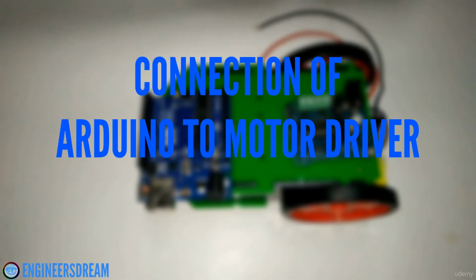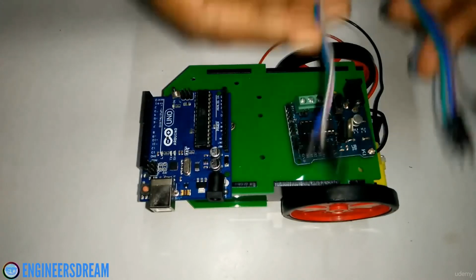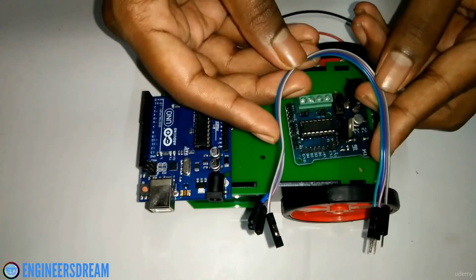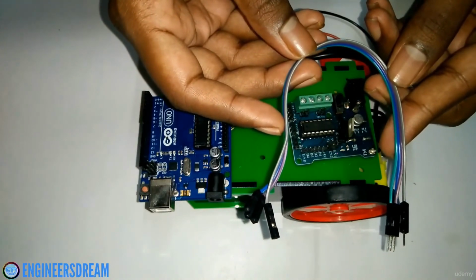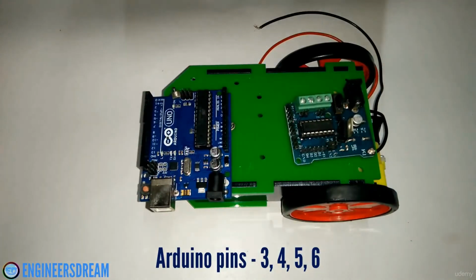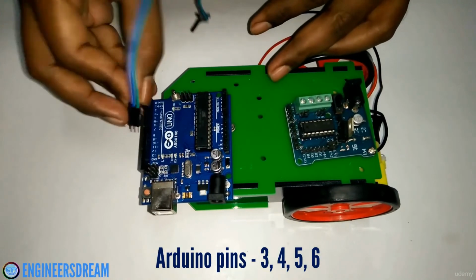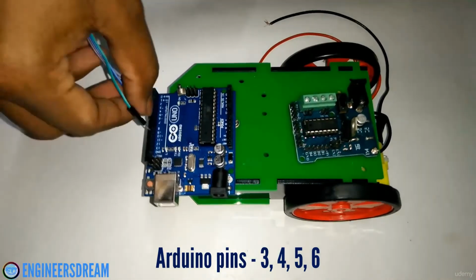So after understanding the working of the motor driver, it is now time to connect the Arduino to the motor driver. First, I'll take 4 male to female wires for connection of the motor driver to the Arduino. Now, for programming the robot, I'll be using pin number 3, 4, 5 and 6 from the Arduino. So I'll attach the male part of the wires to Arduino's pin number 3, 4, 5 and 6.